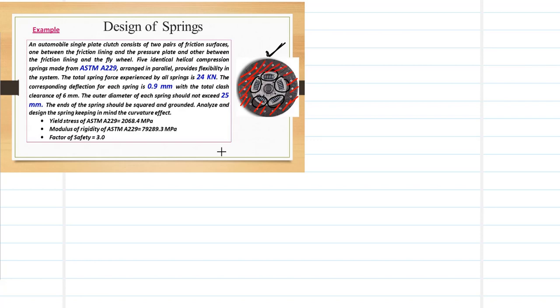So when you press the clutch, this clutch plate disengages the gearbox from your engine, so you can shift the gear, and as you release your clutch, this actually provides contact between your engine and your gearbox, where the gearbox directly transmits your power to your car wheels. There are different numbers of springs in the clutch plate; in the clutch plate of trucks there could be 6 or 7 or 8 springs. Generally in a car there are 4 to 5 springs.